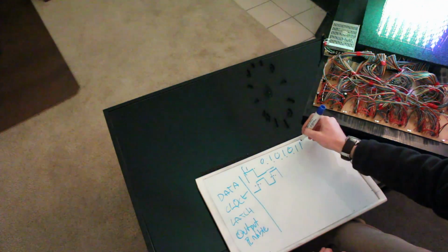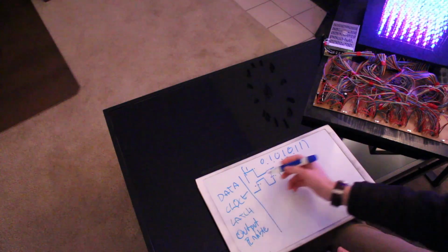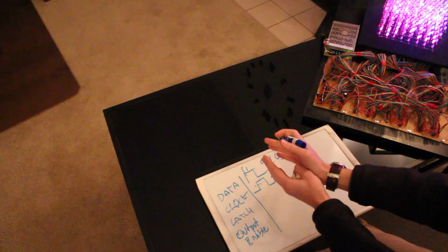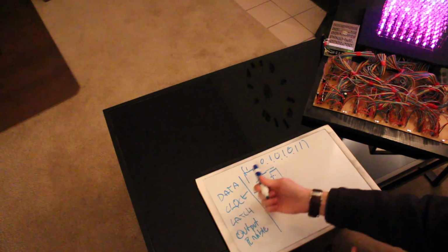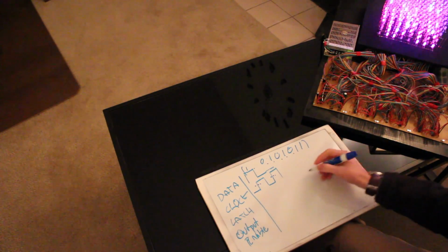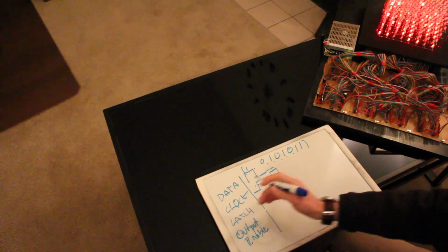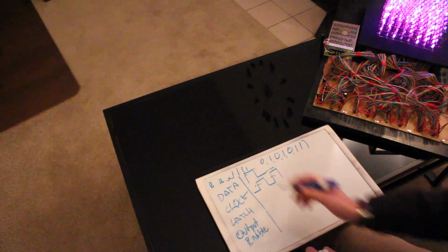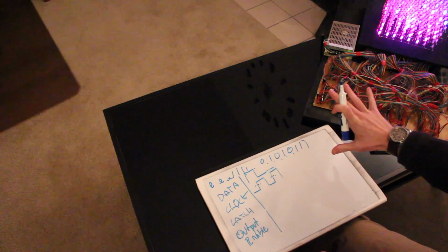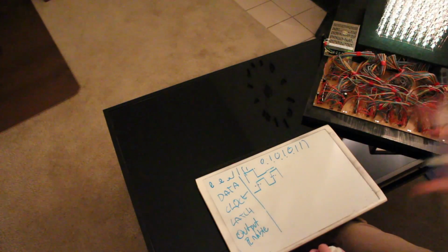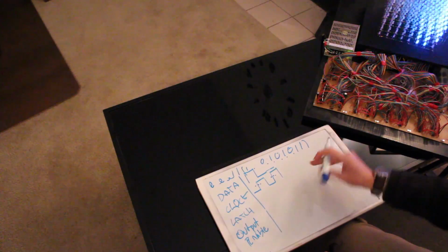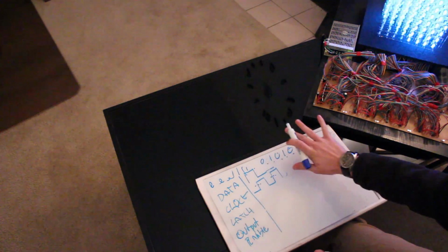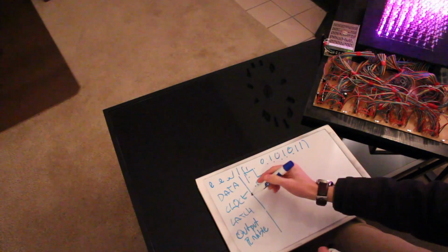Now, if you keep shifting the data, this value here would just go to the next one, so this ends up being on the last one. And then you have another value that you shift in, and that would be somewhere over here. So you have another 8 bits there. Once you get it all shifted in, you've filled up both shift registers, that's 16 bits of data. Each one is a bit. So that's 2 bytes of data. You clocked it all in, data's done. These 2 pins can chill out, they're done.